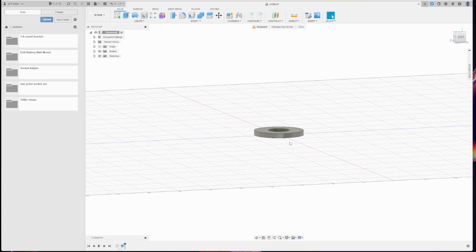So the hope is here this part will go over the pipe, be able to be split, clamped down on the pipe, and fasten the pipe to the wall in a way that my spout can be installed and then caulked around. And all of that whole combination will hold everything together and everything will work as it's meant to be.